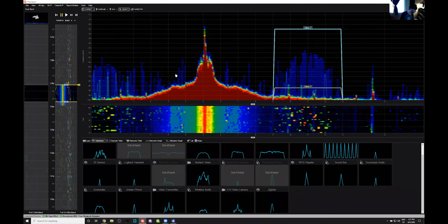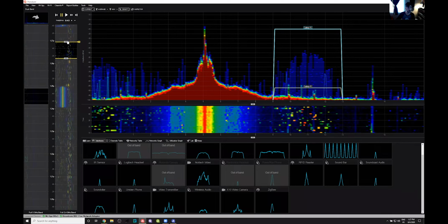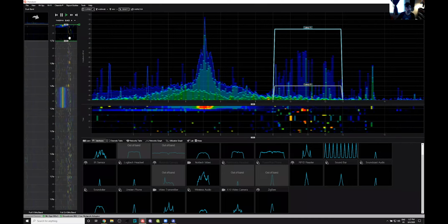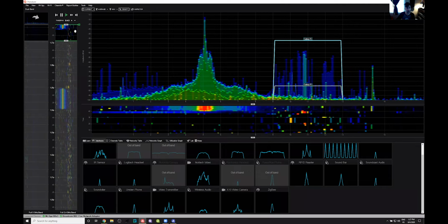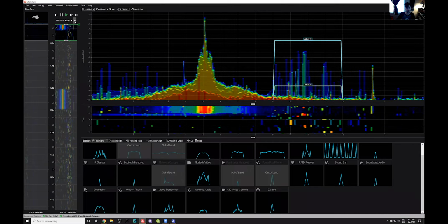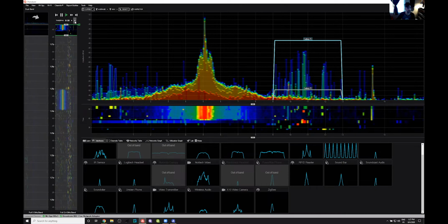Let's say that we don't know where it is quite yet. I'm going to reintroduce this source of interference. Starting to talk again. I kind of want to show you guys how to use the device finder. And so if you scroll up here, I'm just going to go back to real time. I just put my time span at the top left here to the last 43 seconds. You can adjust this as much as you want. I'm going to switch to 30 seconds.